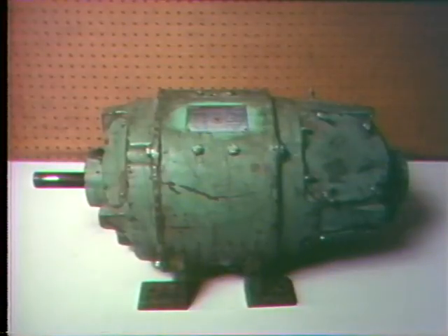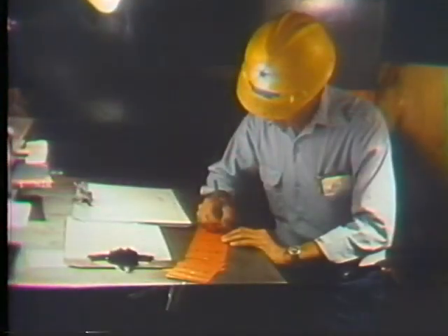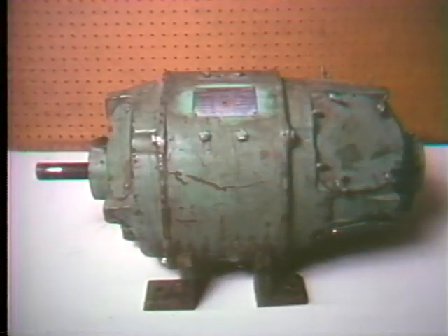We're going to go over three major sources of problems in DC motors: brushes, brush riggings, and commutators. We'll cover brushes and brush riggings in this segment, and we'll go over commutator maintenance in the next. We have this motor in the shop, and we'll use it to demonstrate good maintenance practices. If you are to make repairs in place, you must follow the plant's tag-out procedures and verify electrical isolation before you start work. This is a compound DC motor.